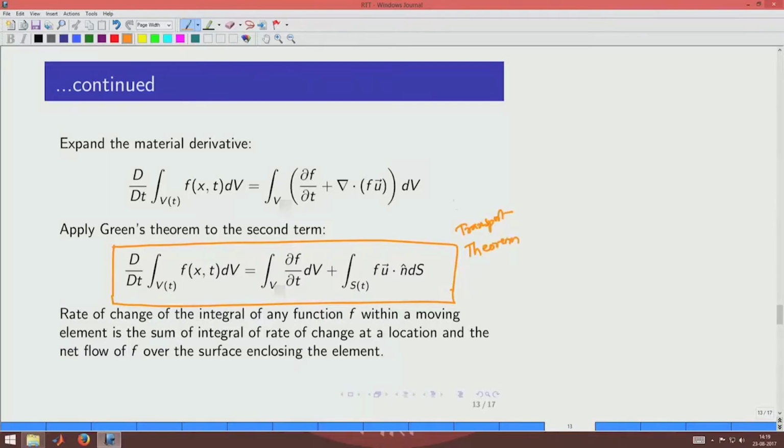We often call it the Reynolds transport theorem, RTT. Very often people refer to that as RTT. So, RTT is this particular expression. You could then substitute various quantities for small f and see how the expressions turn out to be, and those are the applications of the RTT. Let us just take two applications because we need them immediately for our next few sessions.